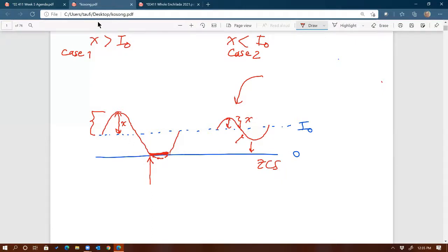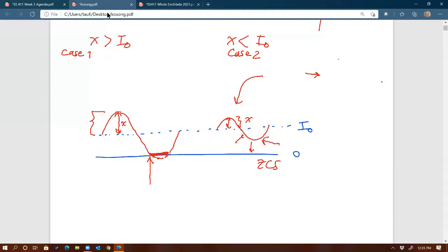Can I ask a quick question? Yes. When it doesn't hit 0, is it oscillating back because we're technically waiting for it to hit 0, or does it not hitting 0 have some consequence in the circuit that makes it bounce back? Because of the way we have the circuit, the circuit only allows positive current. So this is still positive current through the inductor, and it's going to keep oscillating like that. Exactly. So the circuit would never change its state from resonant to state number 3. It will just remain as a resonant circuit. So basically the circuit's not going to work. Does that make sense? Yes? Yeah, that was the piece I was missing.